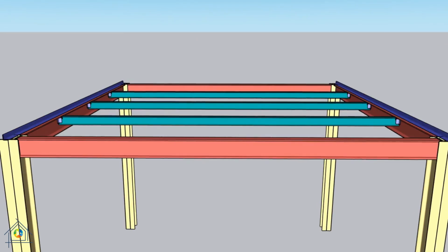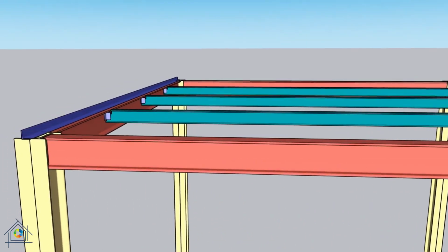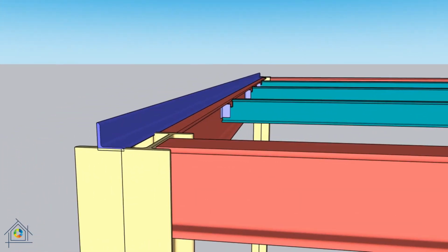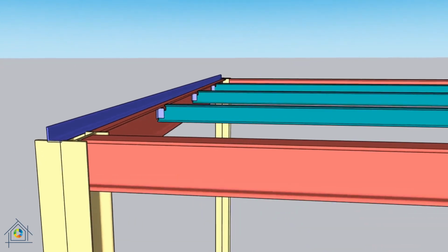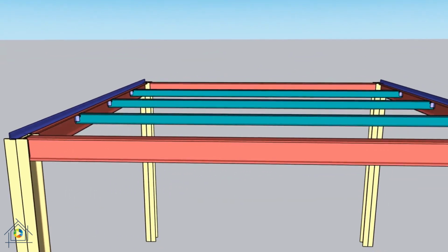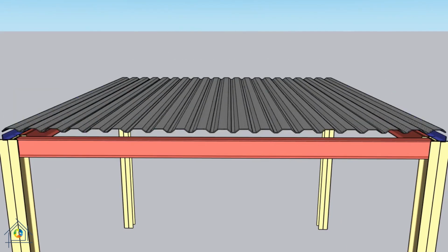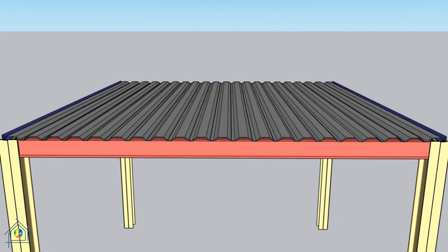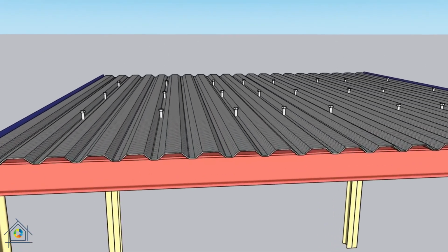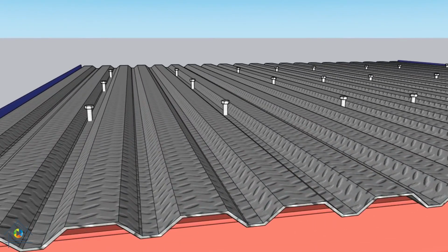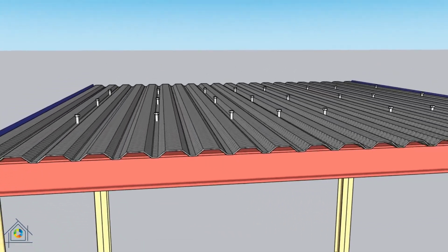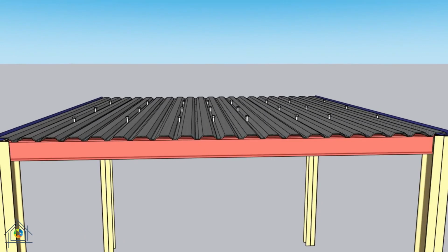To implement the galvanized trapezoidal sheet, which is known as the steel deck, a 6 cm angle is installed on the main beams with a welded connection. Then the steel deck is implemented between the two angles and on the beams. For proper connection of the steel deck to the beams and also for the uniform behavior of the concrete and steel components, shear studs with appropriate diameters and distances are used with a welded connection.